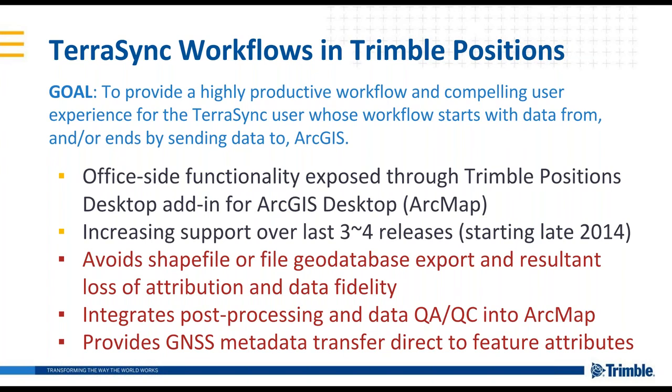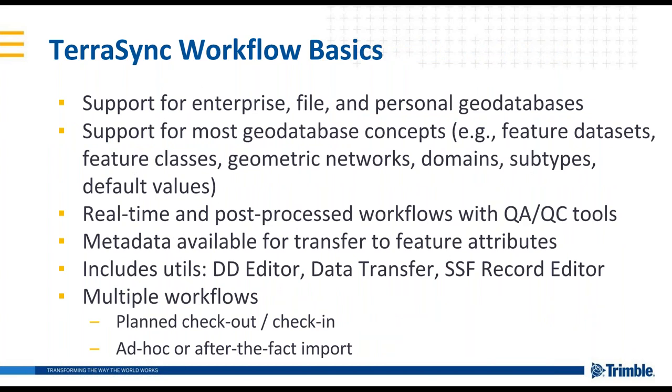After you collect data and do your QA/QC, you want to update those high accuracy geometries back to your Esri geometries. We also give you the option of transferring metadata, data about the GNSS, into those feature attributes too, such that your Esri feature is stamped with the accuracy value, the feature heights, things like that.